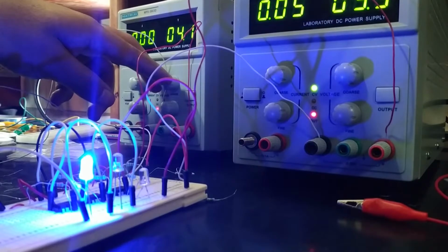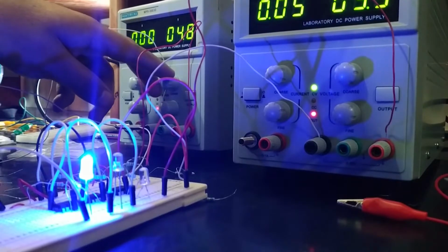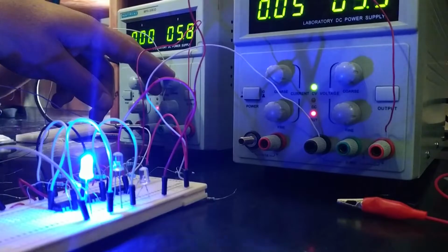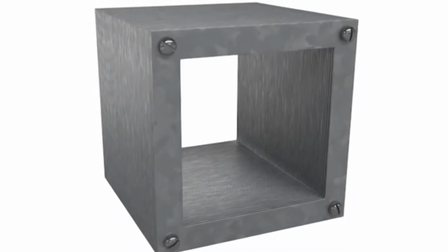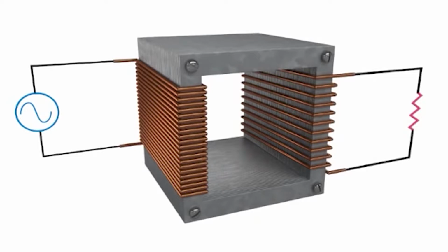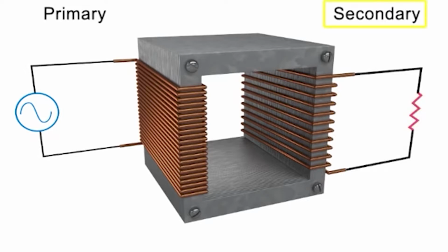So, to transmit the electricity over long distances from the generating station to customers, the voltage is increased. Generator output voltage is usually 25 kilovolts or less. Step-up transformers outside the generating stations may increase the voltage to 230 kilovolts, 500 kilovolts, or 765 kilovolts. The voltage may be increased to other voltages as well, depending on the individual power system and the national standards at play.